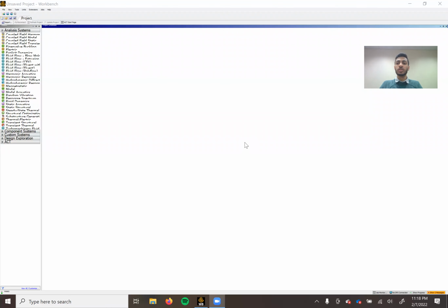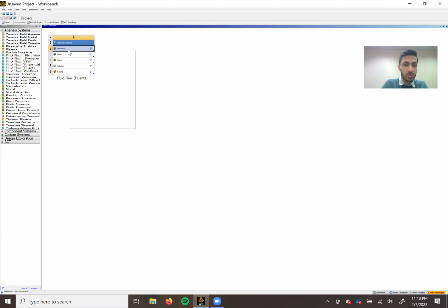All right, so this is going to be my video for project 1 in Design of Aerospace Experiments, creating the 2D wind tunnel. I've already got Ansys Workbench opened up, so we're just going to get right into it. I'm going to drag out a fluid flow project and throw it right in there. And we're going to start by going to geometry and doing a new design model in geometry.